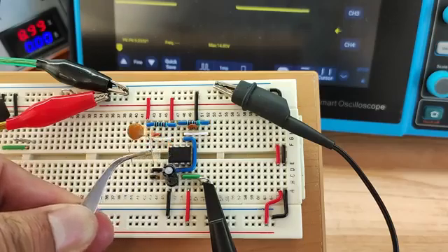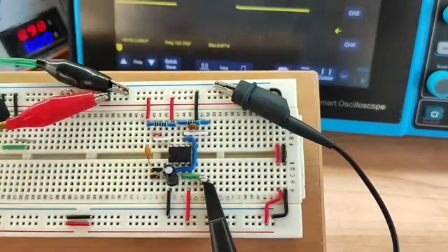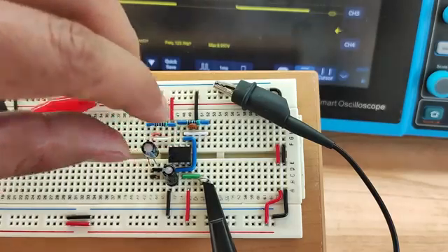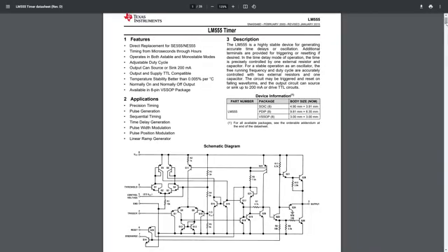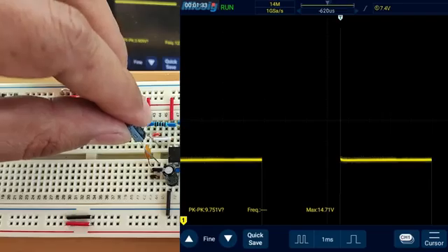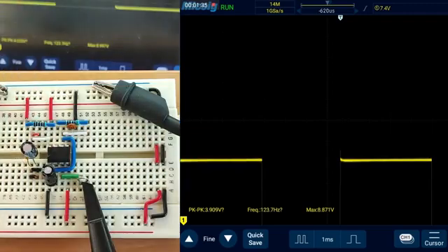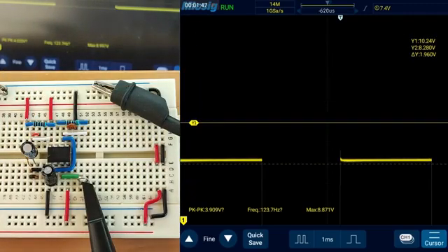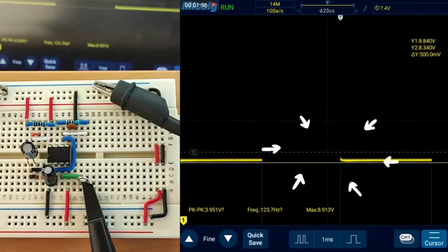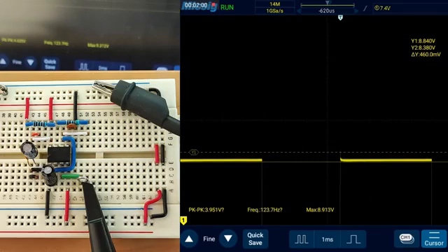I'm adding 2 capacitors at the power lines of the integrated circuit to see the effect. Why 2? And how did I know the values of each of them? Well, because they are prescribed in the datasheet of the manufacturer. The final square wave looks much cleaner. The reading this time for the noise amplitude is only 400 millivolts. Compared with the previous one, it is way lower.